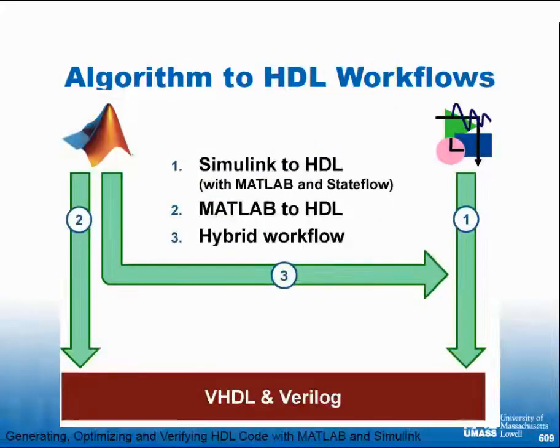So as a workflow, we do Simulink to HDL, MATLAB to HDL, right? These are really 1A and 1B. And then 3 is the hybrid workflow where we have our own design, the MATLAB design, and we bring them together to create Verilog, I'm sorry, VHDL. I'm just going to say HDL instead of saying both of those all the time.